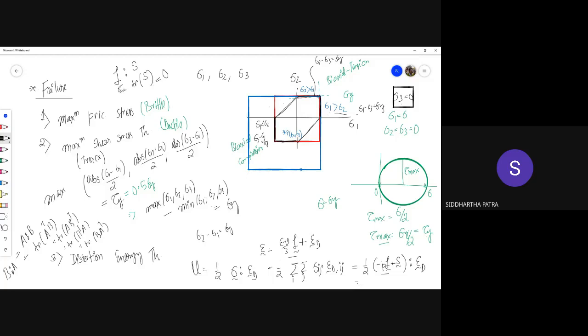This is in a metric space, but even in the principal coordinates we can represent, let's say, a hydrostatic axis that makes equal angles with the principal directions. And then there is a deviatoric plane which is essentially normal to the hydrostatic axis. Because of that, if I take any line on that, any deviatoric stress and any hydrostatic part, the inner product, or the dot product over here, is always going to be zero. So they are literally orthogonal to one another. And so basically what I'm trying to say here is this is only S inner product epsilon d.